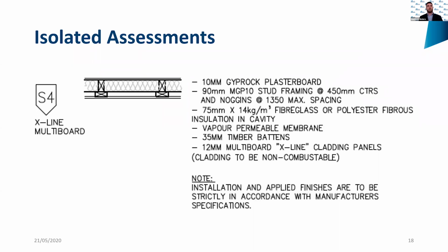The fire engineering report did deal with some reductions of FRLs in other aspects of the building on ground floor. However, it didn't reduce the FRLs or permit a lack of fire resistance levels for this specific wall. In terms of evidence that was in the section 30 documentation, there was no information to confirm the wall had an FRL using AS 1530 part 4. And this system certainly doesn't appear to be something that would achieve a 90-minute FRL.